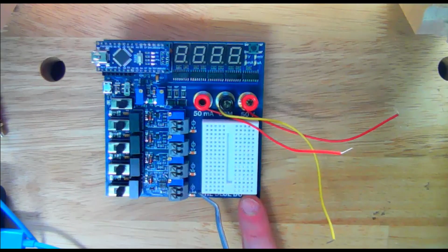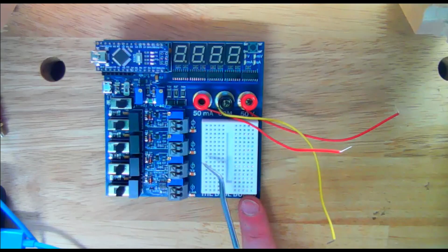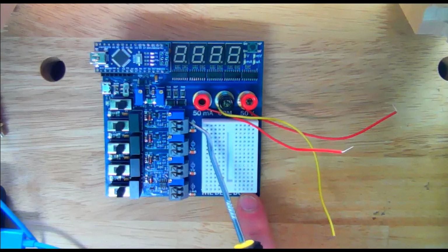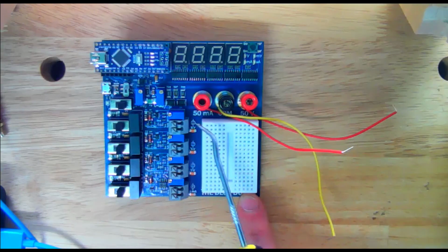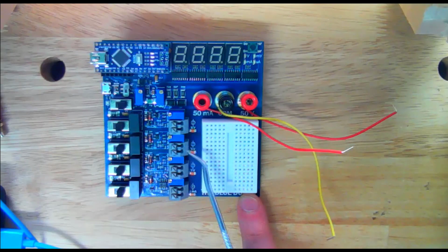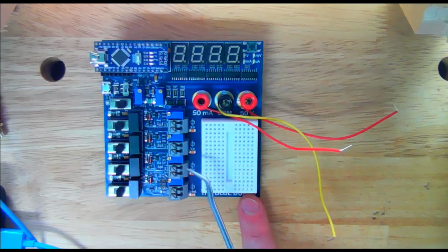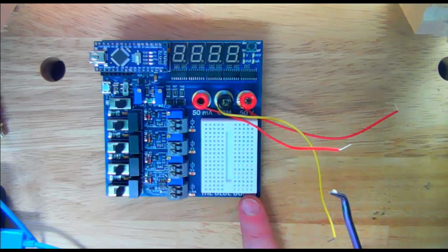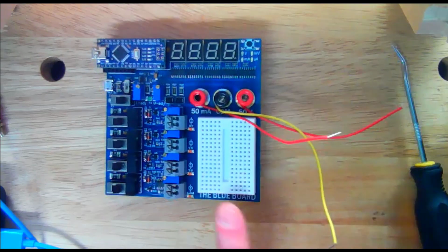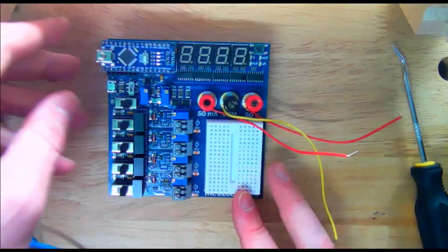You can see on the label here too, there's a little picture and it shows the value. So basically, you can treat these just as any isolated supply. That is to say, the voltage difference between this terminal and this terminal will be 3 volts. The voltage difference between this terminal and this terminal will be 7 volts, etc. You can connect it any way in your circuit you want, and that'll work just fine within reason. There are some limitations, which we'll talk about in later labs.